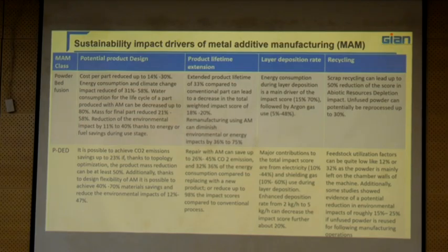One way we can make it sustainable is by looking at how much quantity of powder particles we are using, how much energy we are using, what is the carbon dioxide emission, and how much argon gas we are using compared with your conventional manufacturing process. We need to quantify how much we topologically redesign. If a part is complex, then in conventional manufacturing we need to go for multiple manufacturing processes, multiple scenarios, multiple assemblies, welding or fixtures or rivet joints. But in AM we can go with a single process, but we need to calculate how much energy is required in terms of gas, powder, machine, and post processing, and then we can think of how sustainable it is. That's what we need to know.